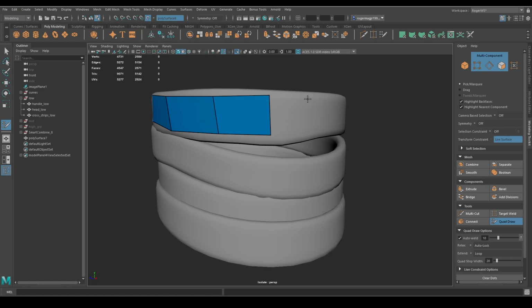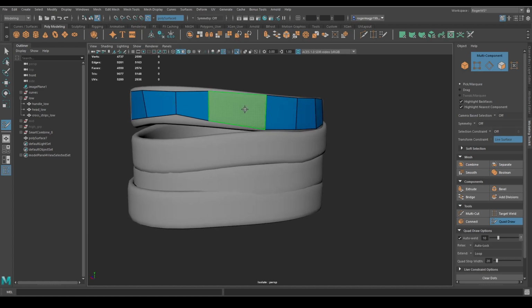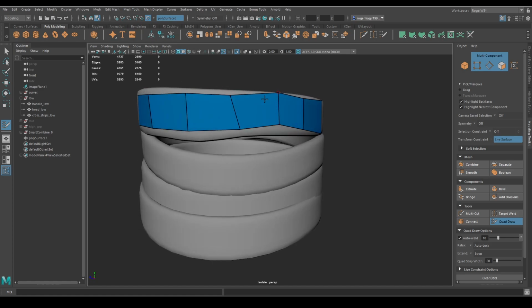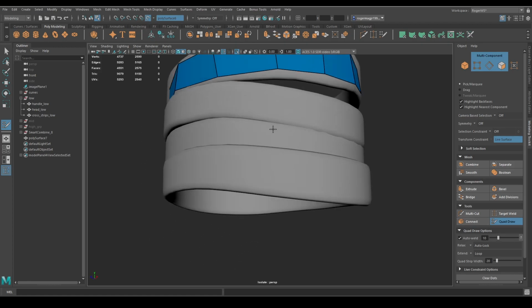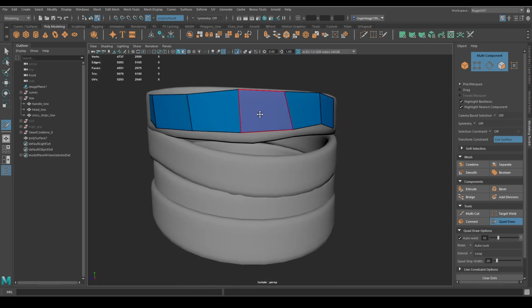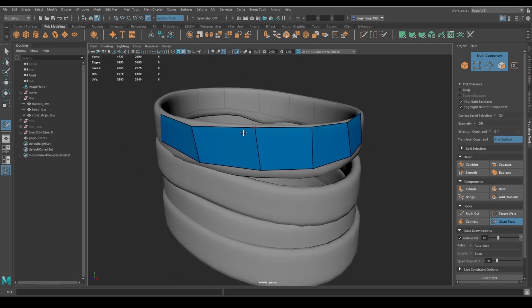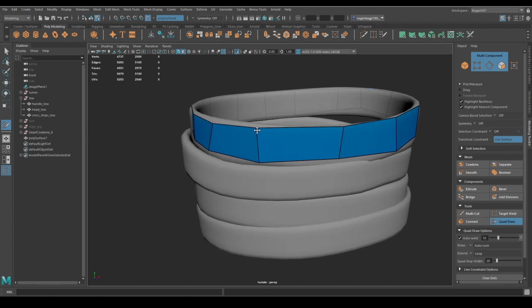And this would also be how you would retopologize, actually, with the Quad Draw tool. By clicking this magnet and then Quad Draw, everything we're drawing is directly on top of this one. So if you look closely, everything we drew is literally like a magnet on the surface of the mesh.